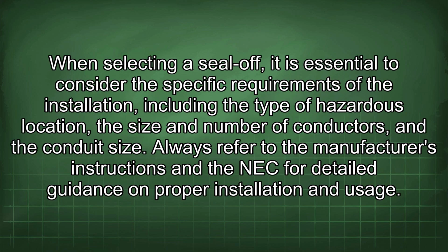When selecting a seal-off, it is essential to consider the specific requirements of the installation, including the type of hazardous location, the size and number of conductors, and the conduit size. Always refer to the manufacturer's instructions and the NEC for detailed guidance on proper installation and usage.